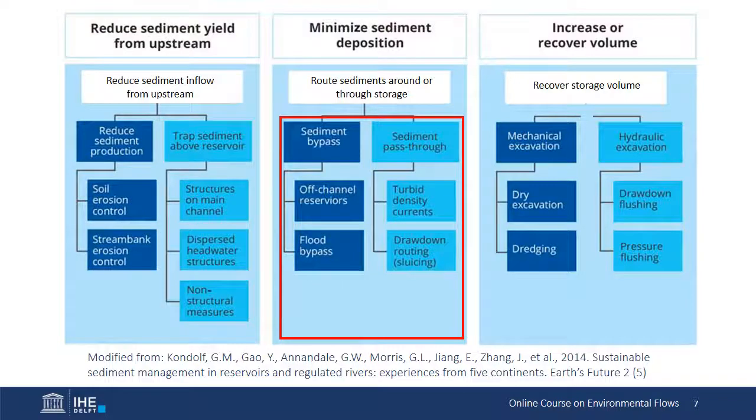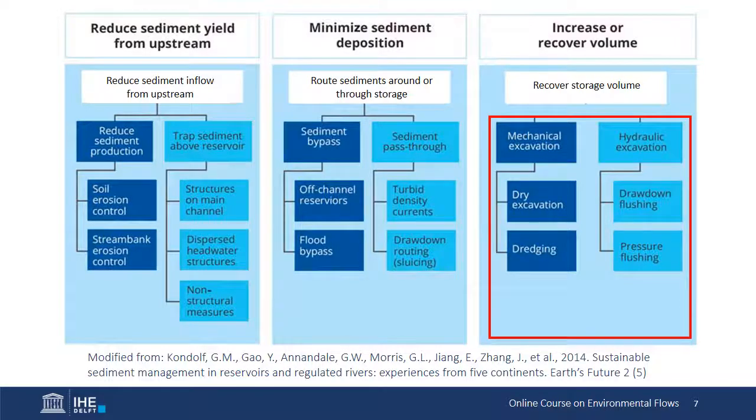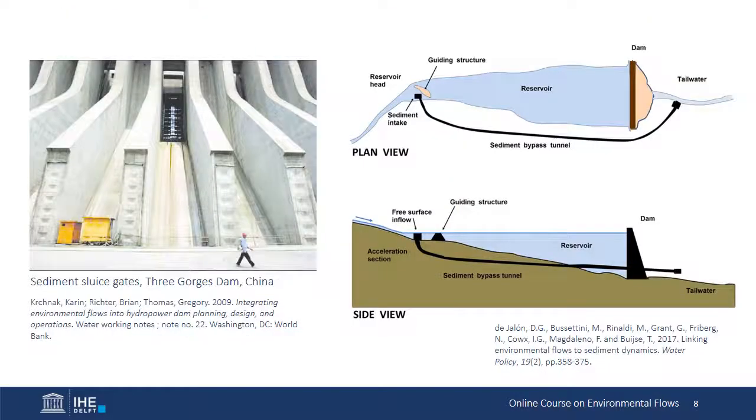A second category of methods has the goal of routing sediments around and through the reservoir. This is extraordinarily challenging and an active topic of engineering research. I'll say more about it in the next slide. And finally, there are methods to recover storage volume. These consist of mechanical excavation methods that are fairly straightforward but expensive, as well as hydraulic excavation techniques that also have their limitations.